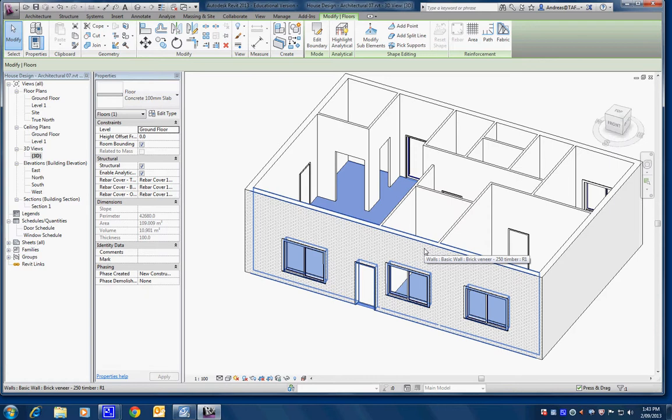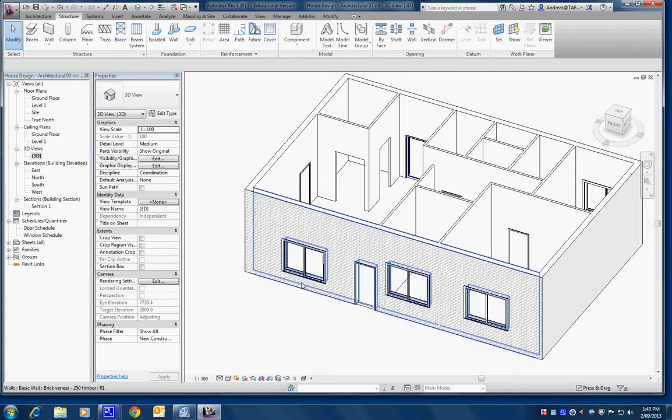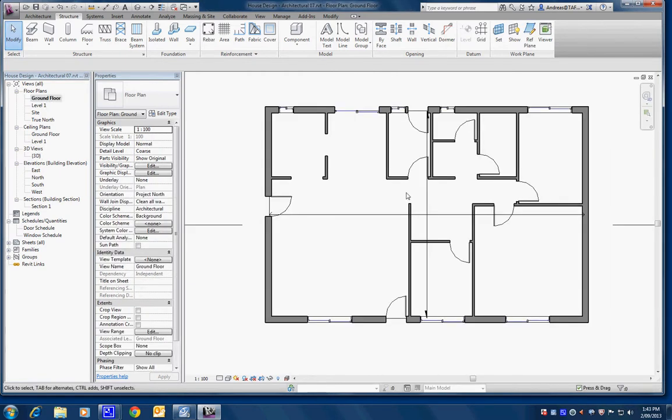All right, so we'll move over to adding a footing now. To add a footing, we've got to just press modify to finish that. Now to add a footing, again, we will probably do this on the ground plan here. And I might just change this to fine to be able to see both leaves of the wall. So footing, where do we go with that?